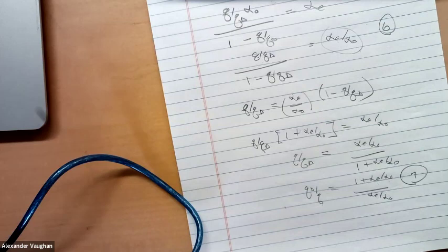To the extent that one is more common than the other, I would say flutter is more common to occur below divergence. In part is because we're much better at predicting divergence with our math models than flutter. So this would be a non-conservative calculation then in design. Yeah. No, you always check divergence. I mean, you always check it. And usually divergence is not critical. Oh, there is an exception, though. I'm glad you asked that question.